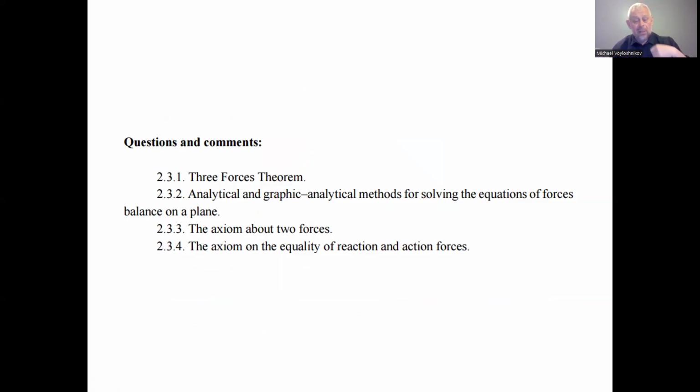Questions and comments. Three-forces theorem: if the mechanical body, the mechanical system, is in the balance and the forces acting on the mechanical system are in one plane, so we consider the plane state of the forces action on the mechanical body, that's why the forces intersect in one point.